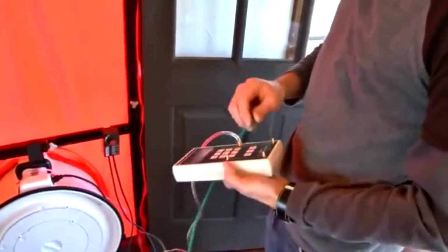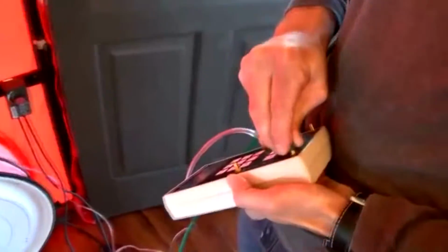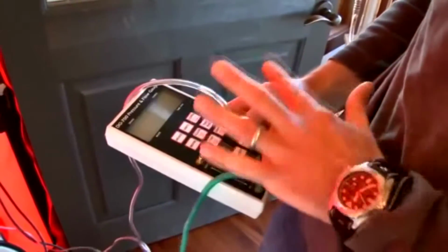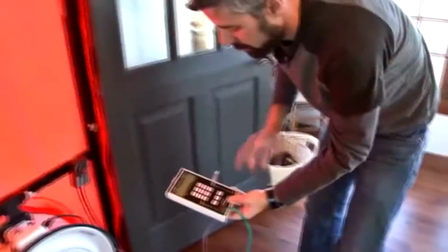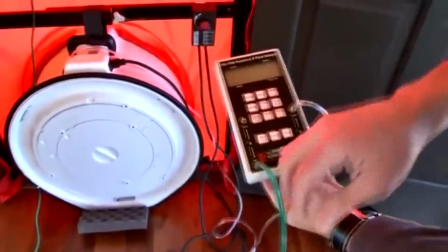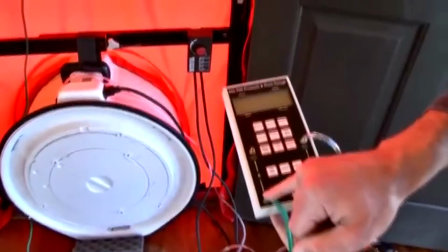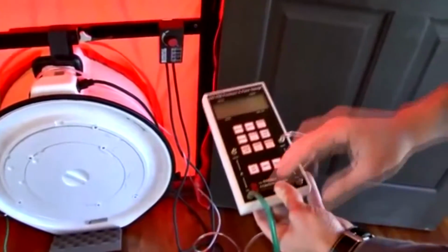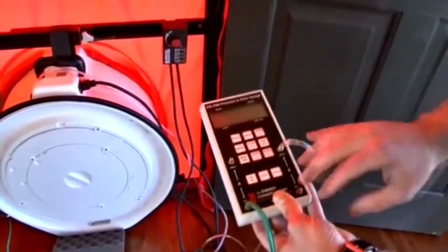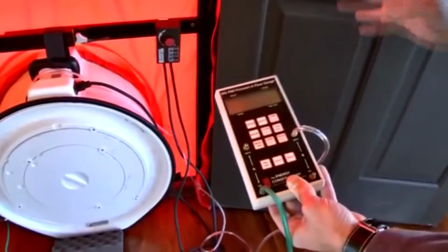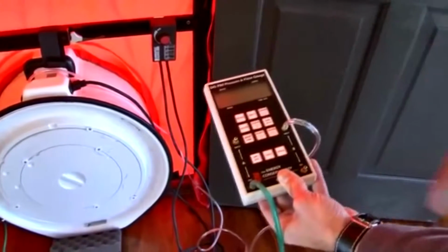So now we're hooking up our outside reference air here, bottom left plug. We've got our fan plugged in. We've got all of our hoses set. We've got our hose hooked up to the fan, measuring that pressure. We've got the hose hooked up to the external environment outside there, reading that pressure. And then we have our reference points here that we're picking up pressure inside the home. So this is all good to go. We're ready to get a baseline.